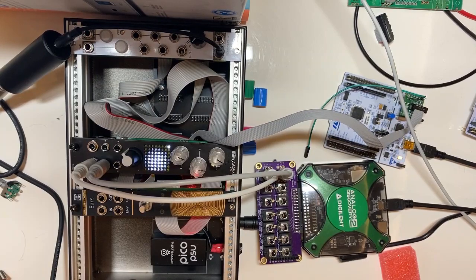So basically this thing has a mid output, I believe, yeah, V mid. Or maybe you can configure one of the other outputs as a mid-scale reference. And then basically you can use that as a reference on the input to an op-amp to bias the, I don't know if that's a good idea or not, maybe Eric can tell me, to basically do a differential output between the mid-scale midpoint and the thing. Then I could do DC coupled, assuming they haven't stuck a digital filter into the codec.